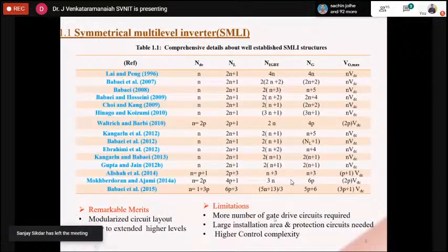But the limitations are that more gate driver circuits are required for the same number of levels, and a large installation area and protection circuits are needed. Of course, as the number of switches increases, generating pulses is very difficult, so there is higher control complexity in SMLI.